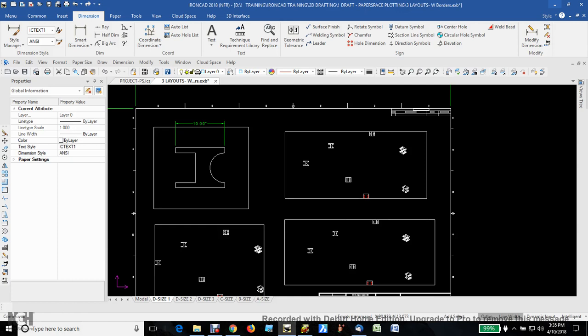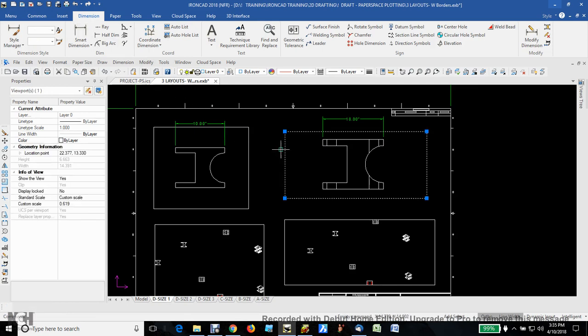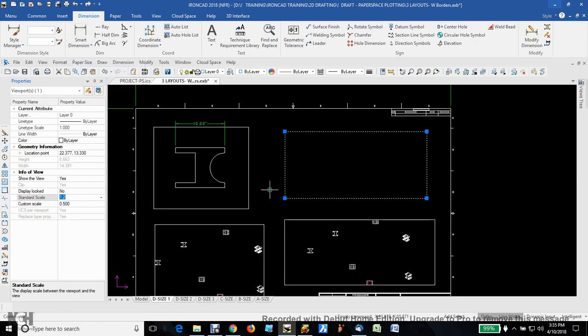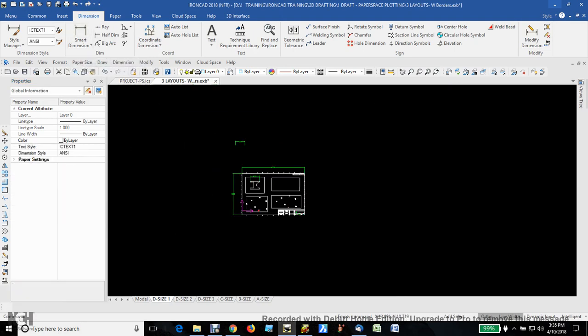So now I come over here, double click inside, and in this particular view, I want the same type view, but this one has the hidden lines on it. So I get that close to where I want it. Double click outside, go to my dimension, add a dimension on it, escape to get out of the dimension command, right click, and then here again I want to make it 1:2 as well, and then off it goes, so it's over there.